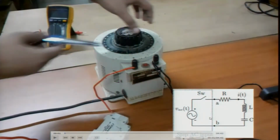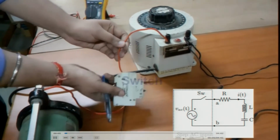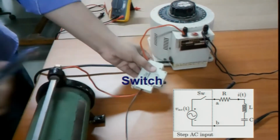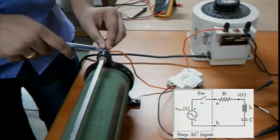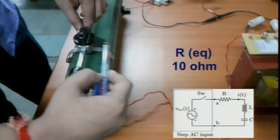Now, if you put AC voltage, this is the second thing we are going to see. What you notice here is we can increase the voltage here, and one of the things of course is this capacitor. If you have done the previous experiment, the capacitor would be charged at 9.35 volt. So, you need to discharge it and get it back to 0 if you want to start from 0 initial conditions. That is one important thing you should remember.